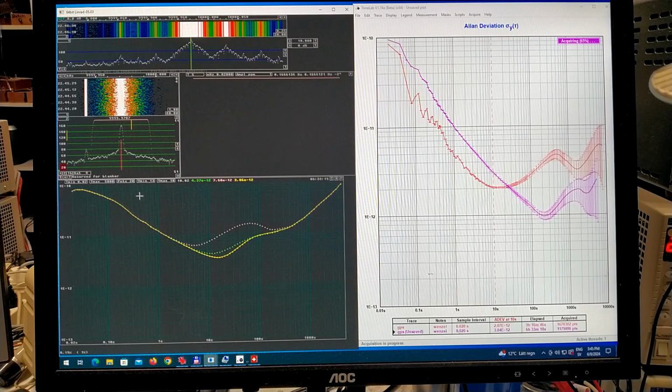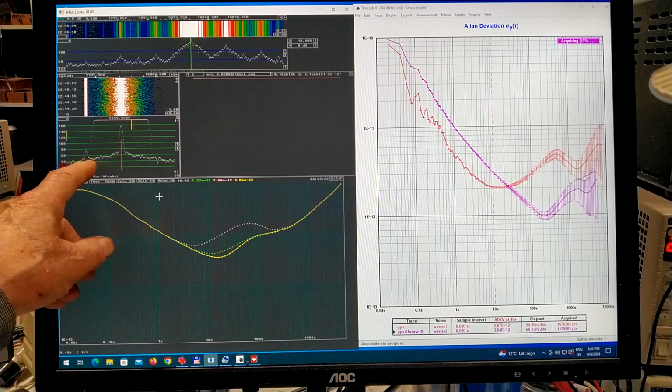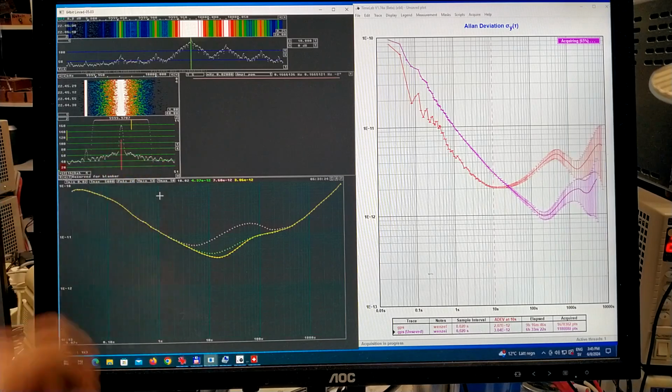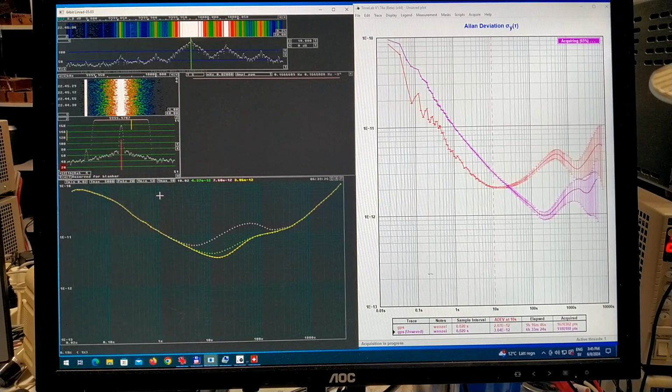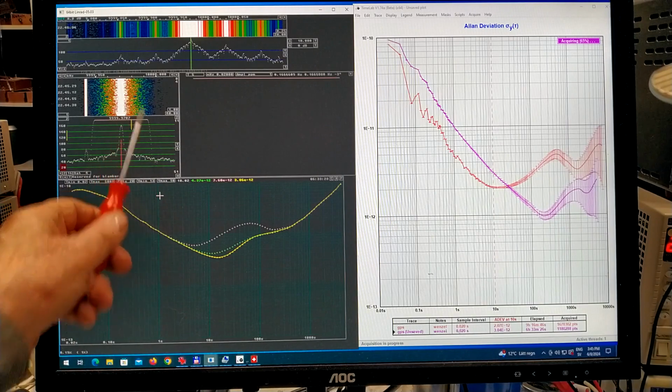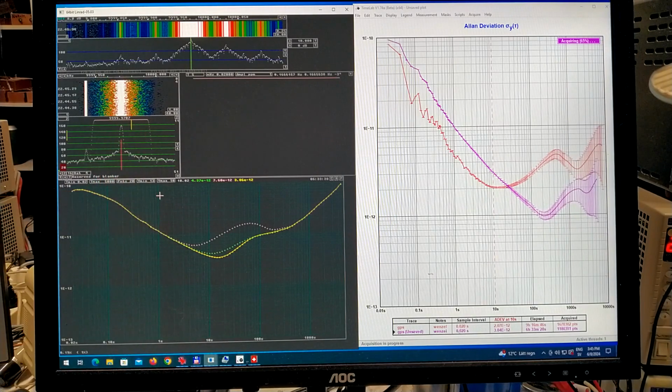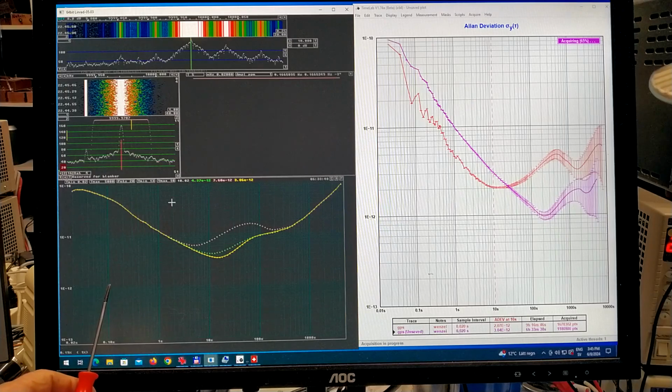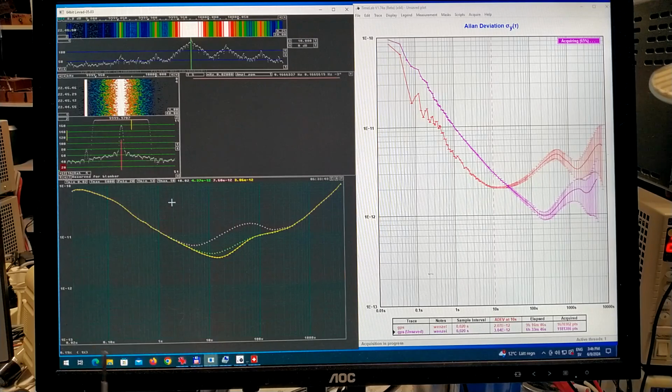We can see in the baseband here the very strong noise from the rubidium oscillator. It was entirely black when I used the GPS-controlled oscillator. The noise is about 100 times stronger, not quite, 50 times stronger at 0.1 Hertz compared to the GPS disciplined oscillator.